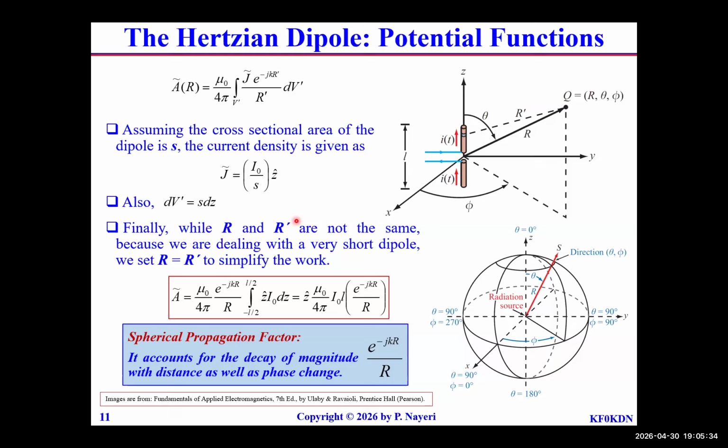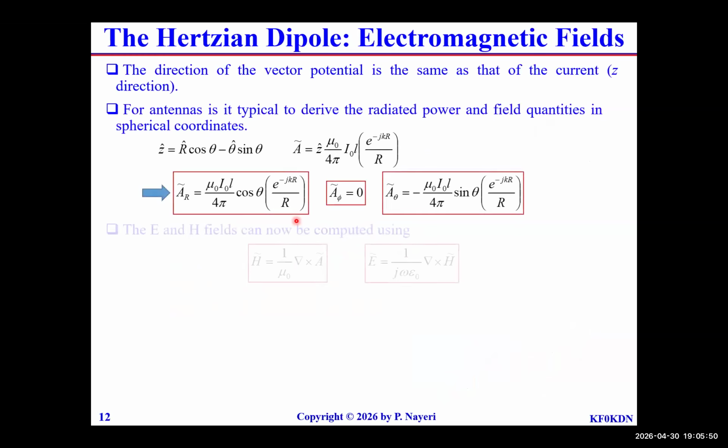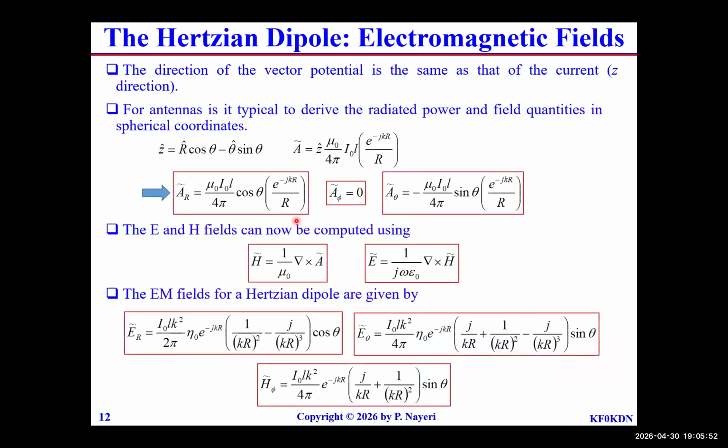Of course, in this case, it's voltage. We haven't talked about power yet, but you can imagine if this is what I'm losing for this auxiliary vector potential, for power it's going to be r squared, which means that if you're away from your antenna, your gain is going to drop significantly. So again, a lot of fun math for you guys to enjoy, but these are the expressions that we can analytically derive for a Hertzian dipole.